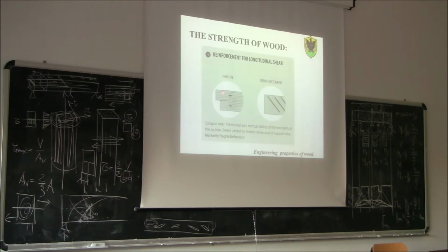The screw must basically tie up the part of the timber above the crack with the part of the timber below the crack. So the screw has a withdrawal strength, a strength against extraction, resistenza all'estrazione. In this case, thanks to the threads, grazie alla filettatura, by working in tension, the screw prevents the sliding of those two parts of wood with respect to the shear crack.